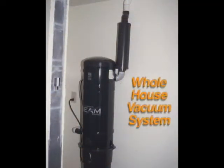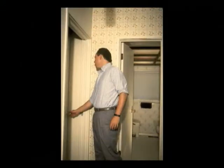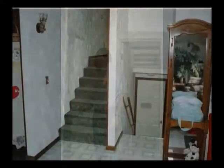Generally, the tighter the house, the more likely negative pressures can be created by internal exhaust that will compete with chimney draft. When interior doors are closed, the main air handler fan can create pressure imbalances within the house. Areas that have more return than supply, whether intended or not, will go to a negative pressure. Different door closures often create a negative pressure in the combustion appliance zone. This is quite unpredictable and needs to be tested. Basement doors can have a major impact. So can bedroom doors in houses that do not have return inlets in all the bedrooms.